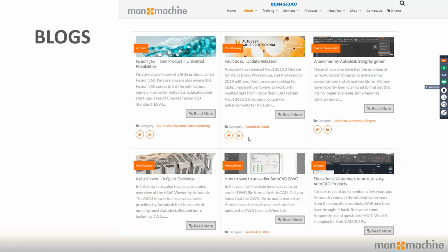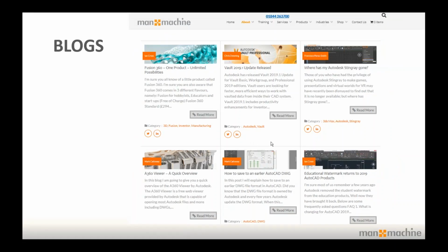If you need to verify if the results are okay, there are a couple of strategies. So in FEA, what you can get, all the time actually, is singularities. They're alternatively called hotspots, where you get areas of intense concentration of stress. Now, in real life, it might be a real stress concentrator, like a corner of a design, in which case you'd see a local plastic deformation, and the stress would redistribute itself. Alternatively, it might be an aberration in the calculation, in which case you might choose to probe near the node which is offending you, and take an average of the stresses in that local area.